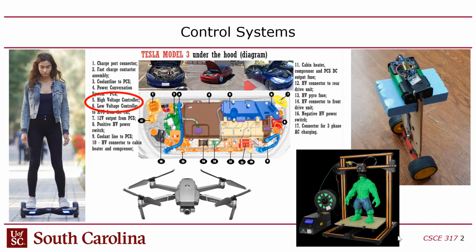And that's the same kind of thing with this robot. This is an inverted pendulum robot that rides on 2 wheels, but it has this kind of inverted pendulum. It's got this structure where it's sort of this narrow piece of board, and it'll balance itself. I've always wanted to build one of these. I never had the opportunity to. But the idea is that this thing has a controller in it that constantly keeps it upright using the wheels. Otherwise, it would fall over.